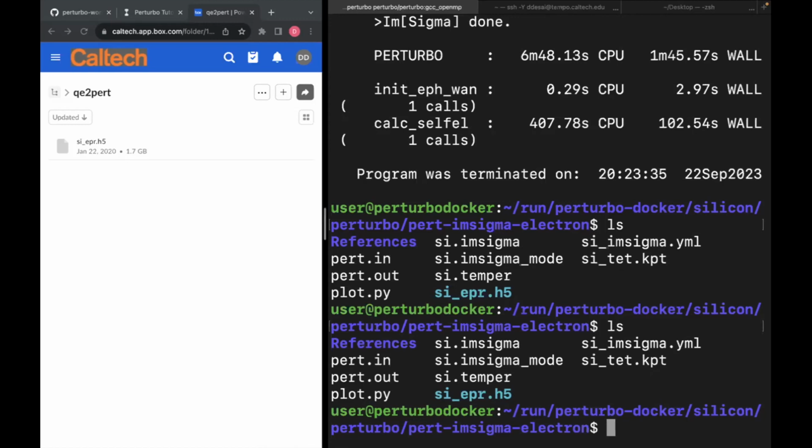How do I tell it is sufficient? What parameter should I look at? Well, if you're, for example, doing 300 Kelvin temperature, then you know just from thermal smearing that only regions within an energy window of kBT are thermally activated. So if you could choose an energy window that's sufficiently large, we recommend choosing an energy window of 6 kBT both above and below the Fermi level.